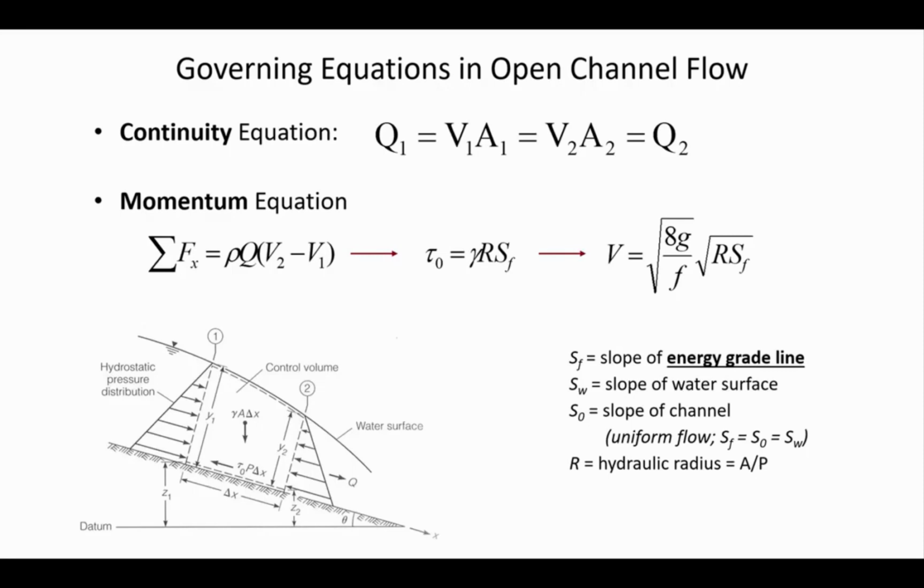And because in the force balance there's less force at 2 than there is at 1, this is moving to the right. So the governing equations that we're going to apply this semester, continuity will continue to be very important, where what we could do is we could do a balance between the flow rate in and the flow rate out at 1 versus at 2.